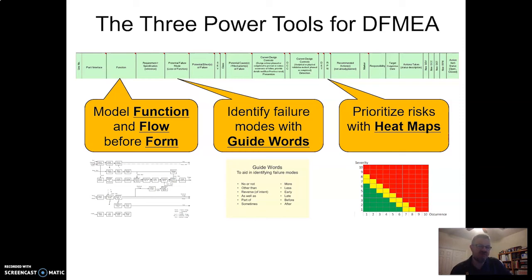And finally, over in the center section, but it's the item here on the right, the RPN is the risk prioritization number. And this is a quantitative index. It is actually computed with numbers to give you an idea of the relative severity of the failure modes you find in your design. What I'm going to cover is that it's generally recognized that the RPN does not have a purely absolute meaning, and we'll talk more about why that is later.